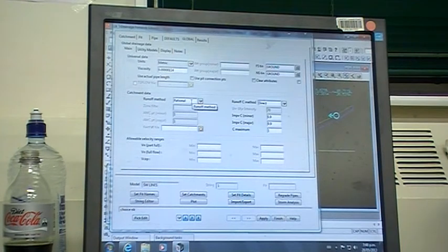Has anyone ever come across this in hydraulics? Did you cover SCS curves? In highway? You did? Oh right, okay. So basically you're assigning, if I say that X percentage of this campus's land is totally impervious, then you assign a value for that, and it runs on a number from 0 to 100 basically, and obviously the higher the number, the more impervious.